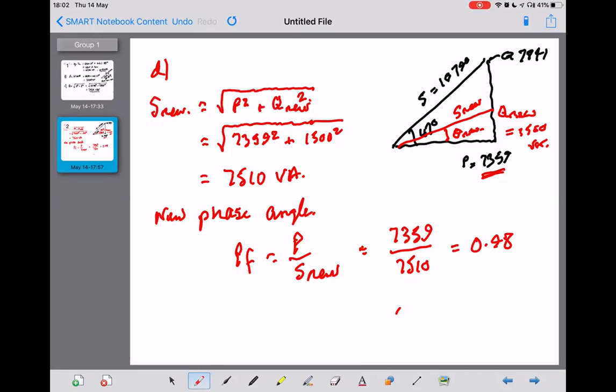And as the power factor equals cos theta, then theta would be cos to the -1 of 0.98, which then gave me 11.5 degrees. And I was starting to wonder, because on my answer I'd done cos to the -1 of that, so I didn't resolve that to 0.98. But you got exactly the same answer as me. Yeah, I got 11.5. You do it in one step rather than two, then, wouldn't you?